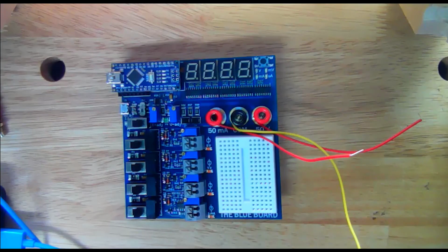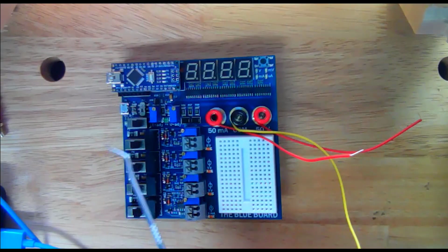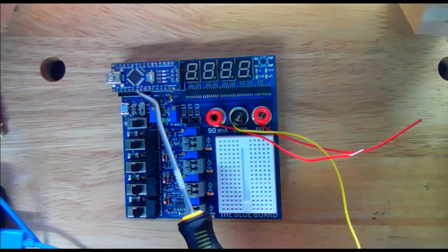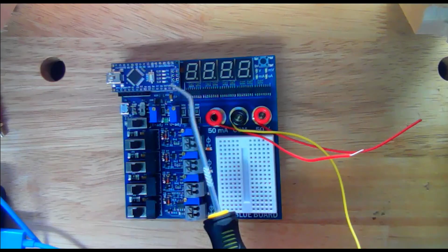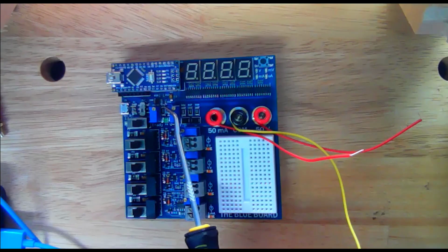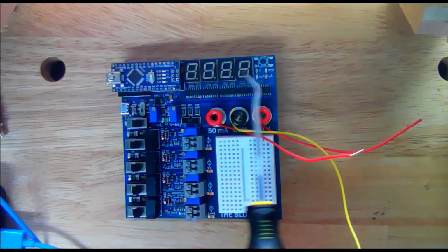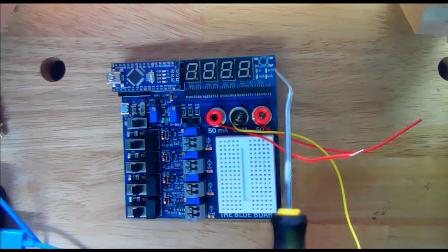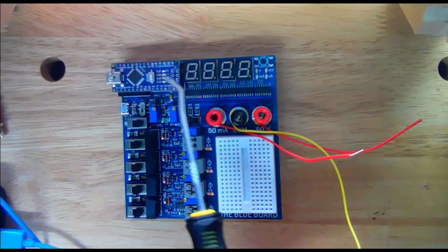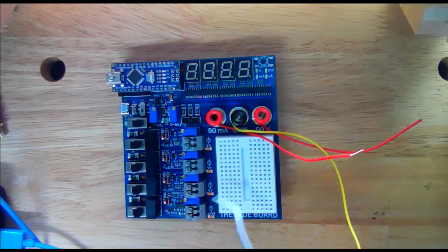So before we power this thing up, let's talk about what we've got on this board. So we have a microcontroller up here. That microcontroller, you might recognize it as an Arduino Nano. All it does is drive the LED display. It reads a value off of an analog digital converter that's external here, does a little math on it, and displays it here. It does some of the switching and detecting button presses and things. It's just the brains. It doesn't actually control our circuit at all.